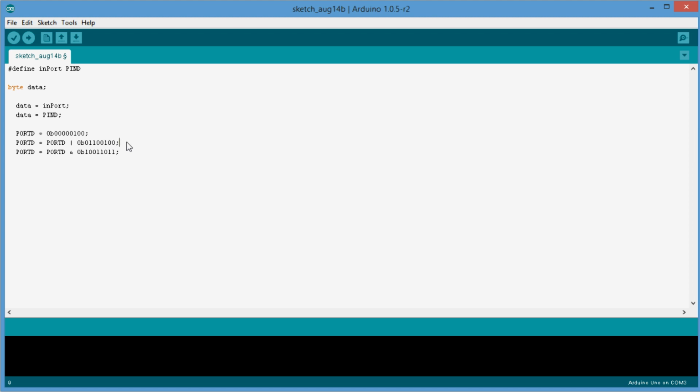But if you really want to get into this more deeply and get really good with your code, you need to start digging deeper and start not using some of those built-in functions with Arduino. And what you'll find is that when you compile those functions, you start using up a lot of memory. They do use quite a bit of code. And by doing it this way instead, you use up a lot less code and you'll be able to put a bigger project into your microcontroller.